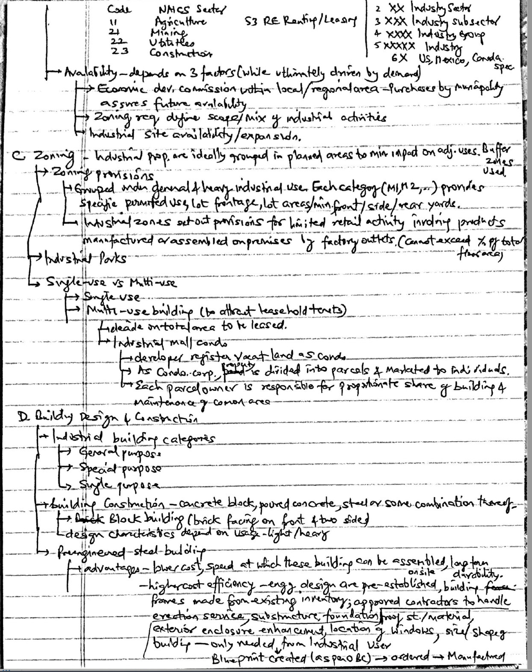Clear span or clear height. The span refers to the amount of floor area that is clear of interference from columns and support walls, and is also of importance to industrial users. The extent of clear span is particularly key to industrial operations, including manufacturing, warehousing, distribution, and storage facilities. An excellent example of a large clear span steel building is a modern airport hangar. Clear height refers to the unobstructed distance from floor to ceiling. Light industrial warehousing facilities normally range between 15 and 30 feet clear height.